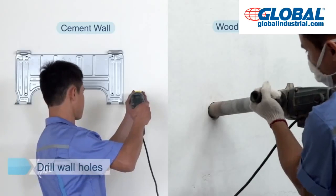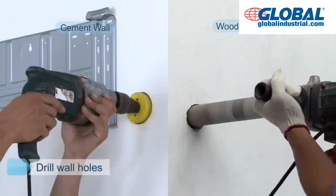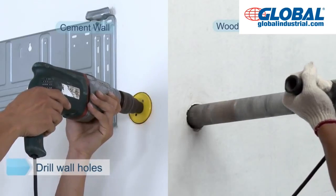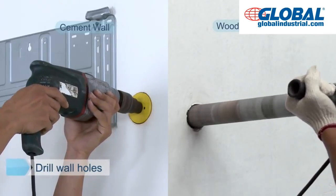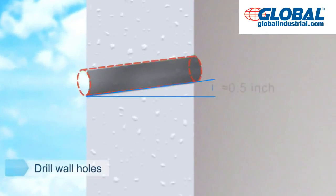Determine the wall hole position according to the exit pipe direction and the expected installation position of outdoor unit. Avoid wires and other foreign materials. Attention should be paid that the inside of hole should be about 0.5 inches higher than the outside. Put on wall socket.